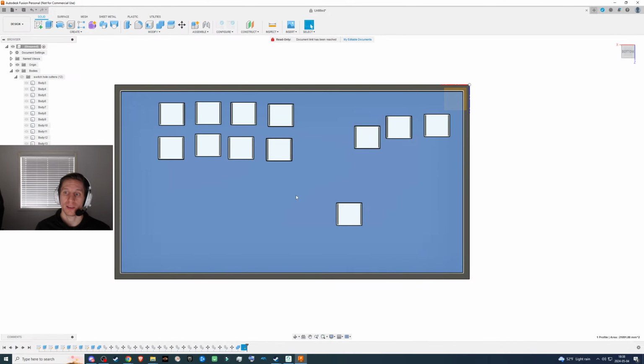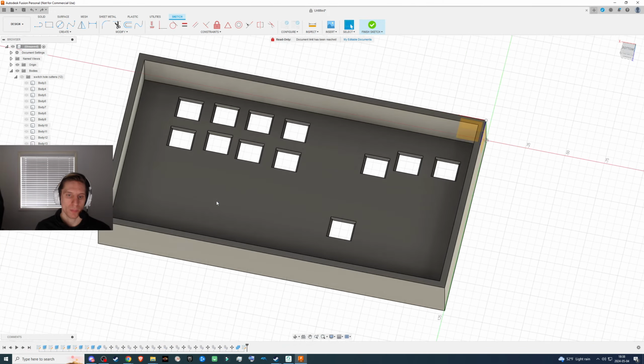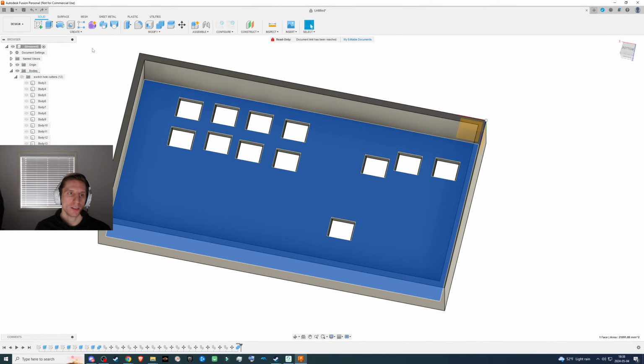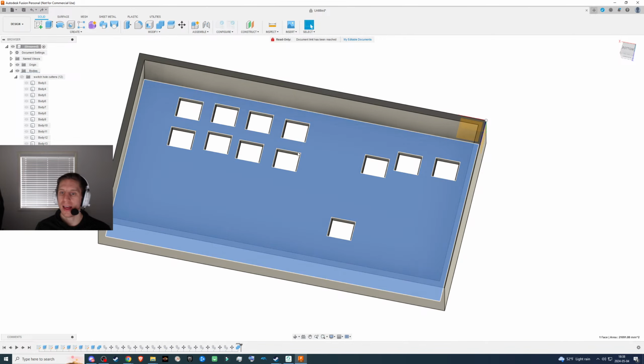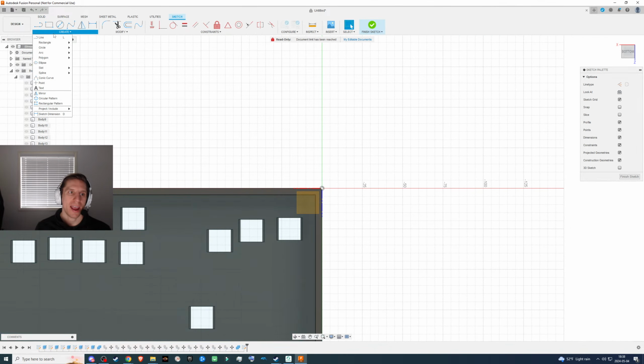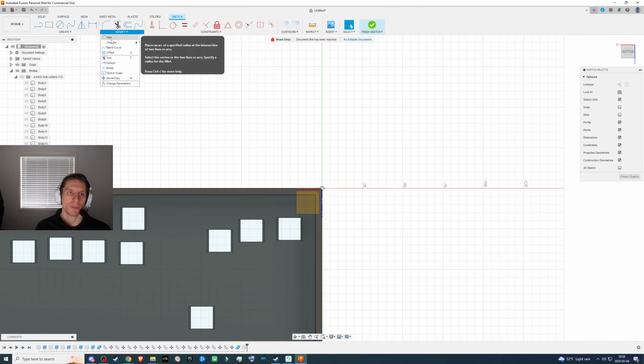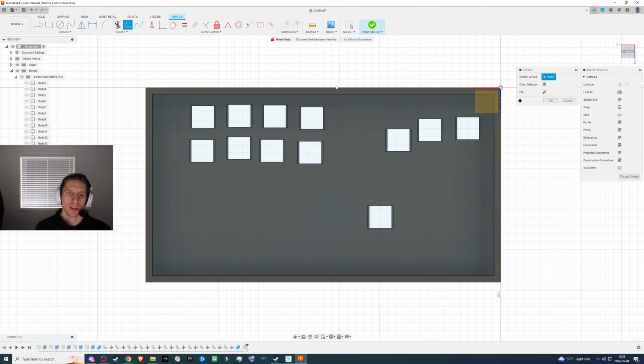Well, okay, so I'll just click this, and if you hit L for line or O for offset, it'll automatically create a sketch and then go into offset. If it was L, you'd be in line mode, but I'm in offset mode, so I'll click it again.